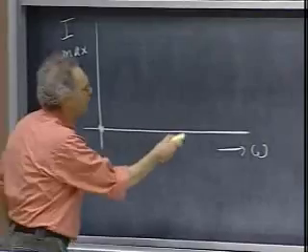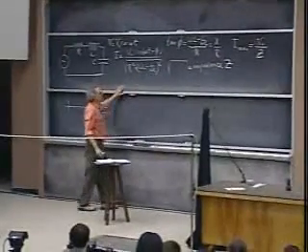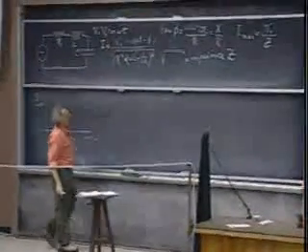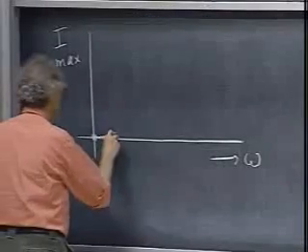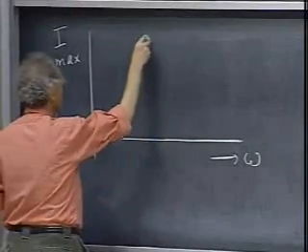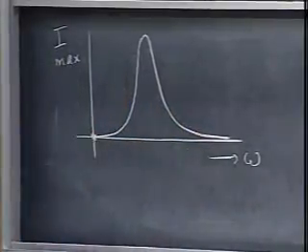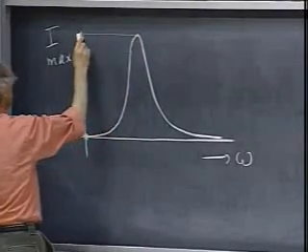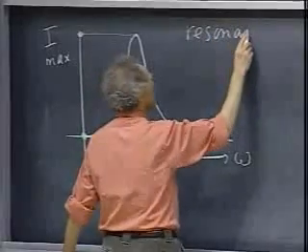When we go to very high frequencies, it is the omega L term that goes to infinity. And so again, Z goes to infinity. So again, I max goes to 0. And for other values of omega, you get an I max which is not 0. And so you get a curve like this, which has the name of resonance curve. This I max reaches a maximum value when the system is at resonance. That's what we call resonance.